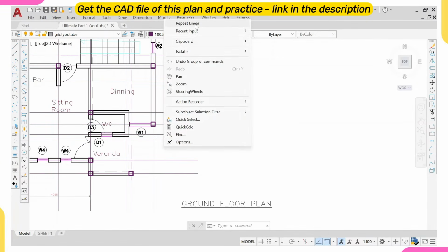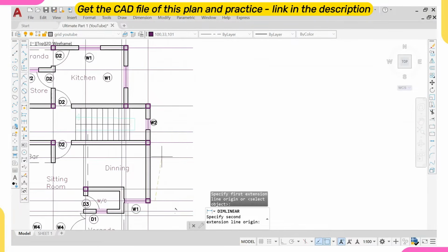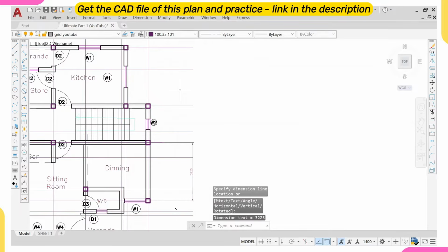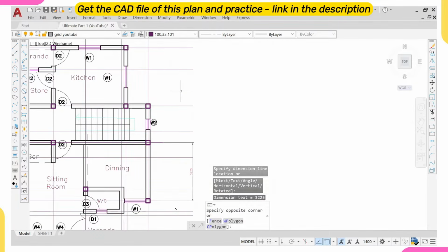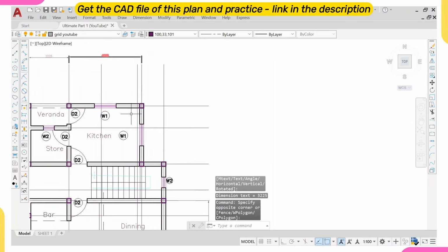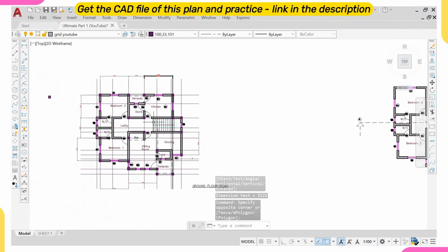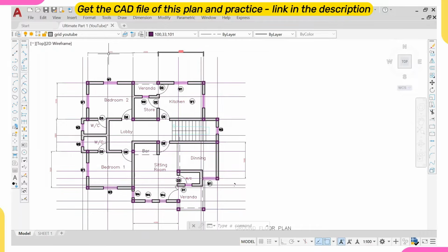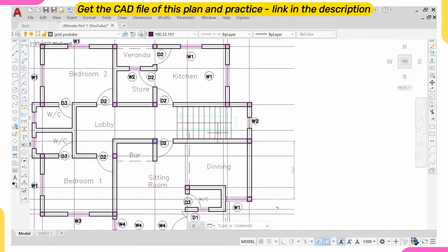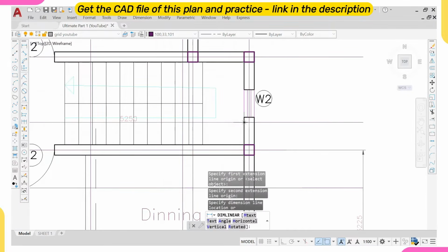So I also click on this line. I'll check from here to here. For me, it's not more than 6 meters, so it's okay. Definitely this will not be more than 6 meters, and this too will not be more than 6 meters. So I've checked my columns and I've seen that they are not more than 6 meters. But we can decide to check from here to this point. I'm having 5.25. So it's not more than 6 meters. So for me, it's okay.